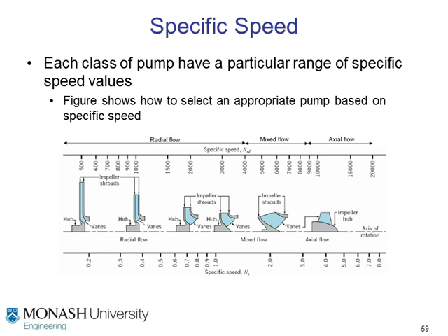The number is 3.5, say, then you look up here. It's 3.5 here. The recommendation is go for axial flow pump, all right. High flow rate, low head wise. Okay. But in other application, you calculated that number is maybe 0.3. Then you go down here. This radial flow pump is the centrifugal pump, right?